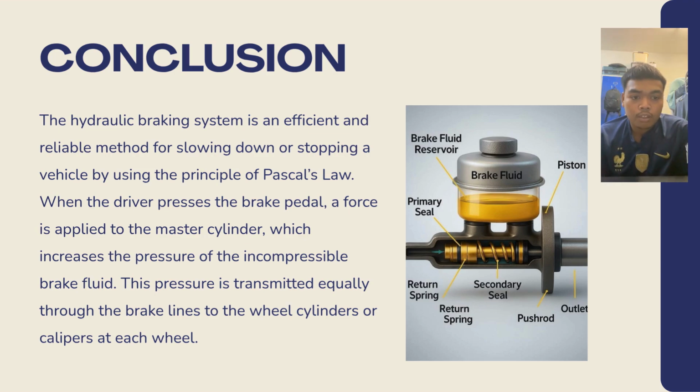For the conclusion, the hydraulic braking system is an efficient and reliable method for slowing down or stopping a vehicle by using the principle of Pascal's law. When the driver presses the brake pedal, a force is applied to the master cylinder, which increases the pressure of the incompressible brake fluid. This pressure is transmitted equally through the brake lines to the wheel cylinders or calipers at each wheel. This illustrates the mechanism of the hydraulic braking system.